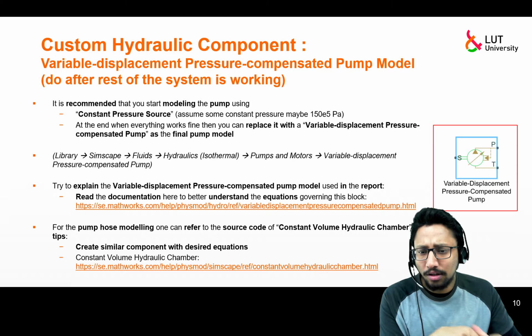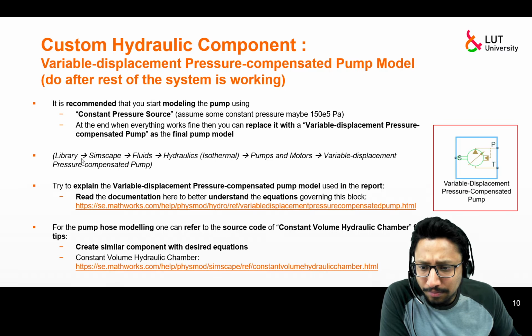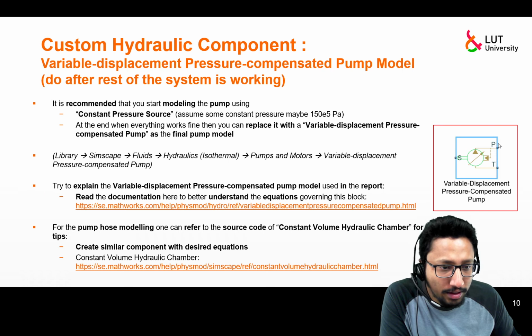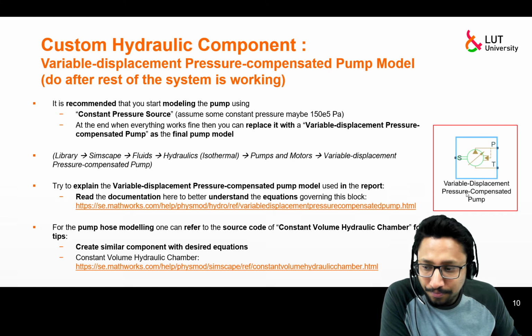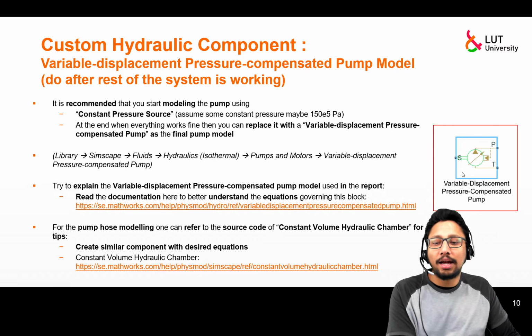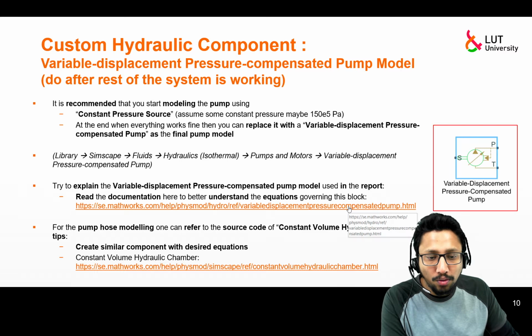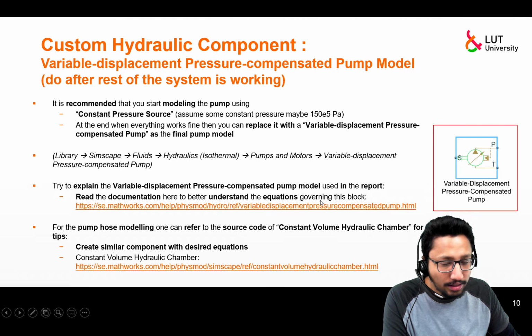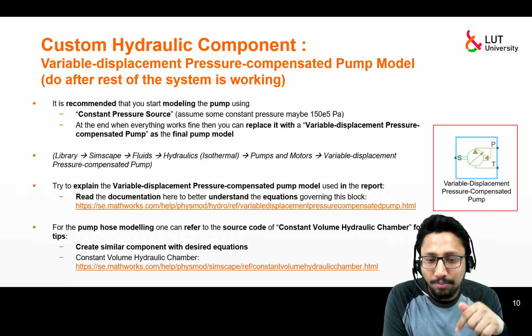You can find the path here. For example, go to library, Simscape, Fluids, Hydraulics, then Pumps and Motors, and you can find this block there. This is how it looks. In order to understand what is happening inside this pump, it is highly recommended that you follow this link. The link will be provided in the description of this video.